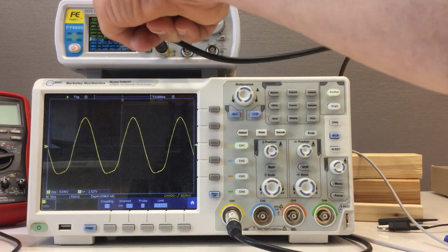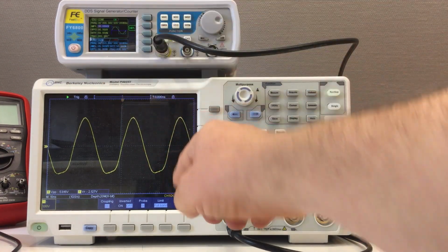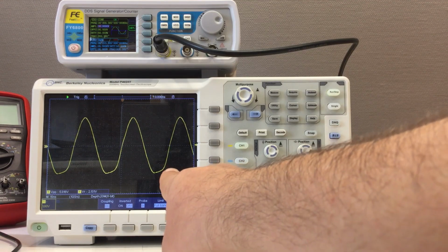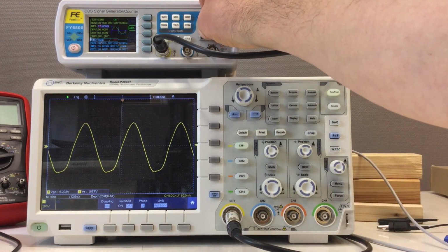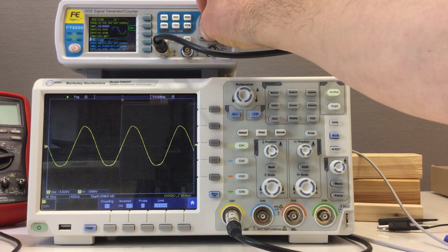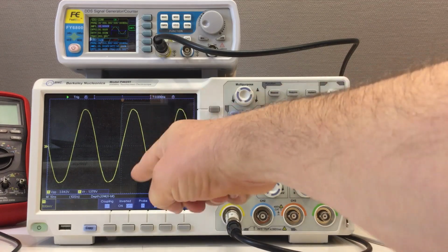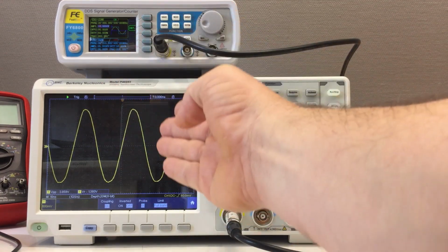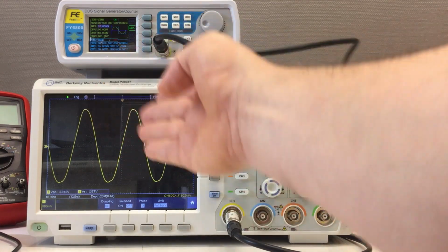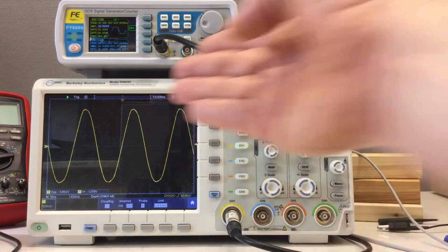And I have here a 20 megahertz sine wave with a set voltage of 20 volts peak to peak, and it doesn't look like a sine wave. We really have to dial down the set voltage to 10 volts peak to peak so we get a nice sine wave, because the output stage cannot drive a 50 ohm load at above 10 volts peak to peak.